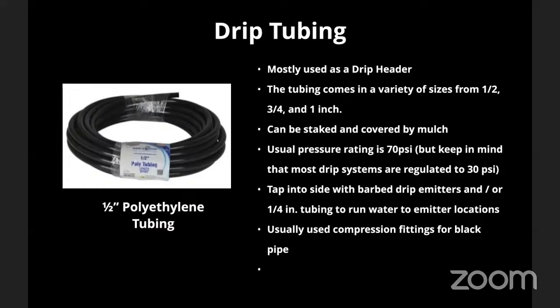And so one of the differences generally between the black pipe and the brown pipe for the solid tubing is that there's a certain fitting type, and we'll look at those fittings later, where you might need to have an elbow or a T or connect to a different piece for the black pipe, and you usually have a somewhat different fitting for the brown pipe. The black pipe is commonly sold in big box hardware stores, sometimes specialty stores. The brown solid pipe is more at the specialty irrigation stores.